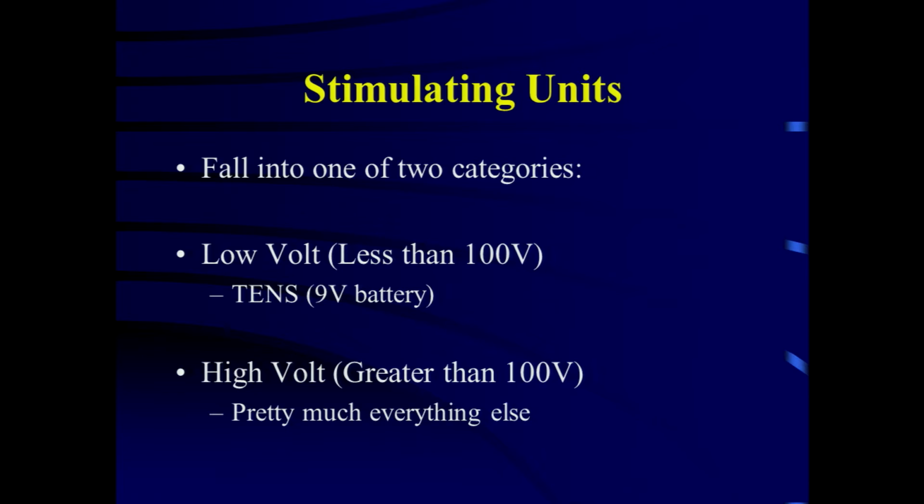This is a very important thing when we go to pulse generators: we have to use some kind of intermediate source of energy storage. Energy can be stored either in a magnetic or an electric form, so you can use either a capacitor or an inductor. But an inductor stores energy while current is continuously flowing, and current flow requires a closed circuit, and any transfer of that energy to another circuit would call for interruption of that circuit.